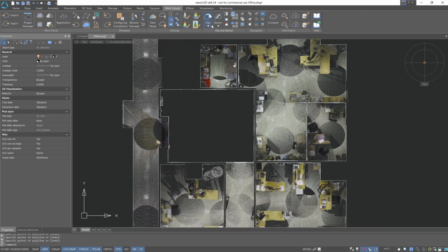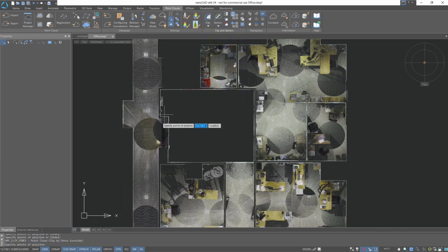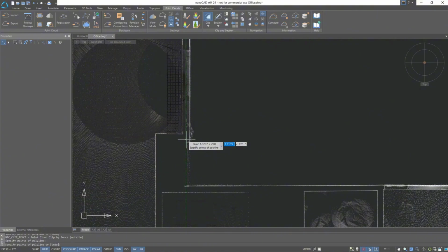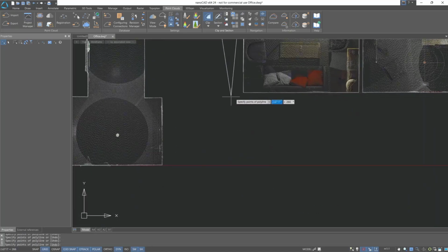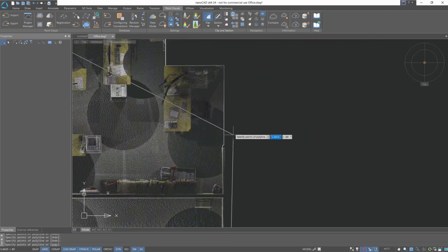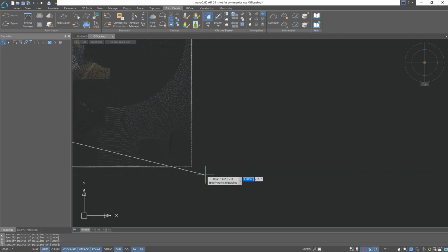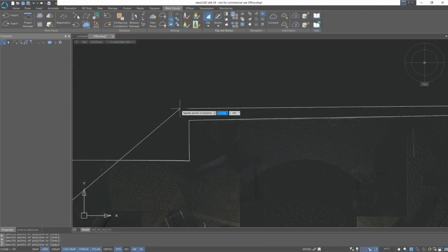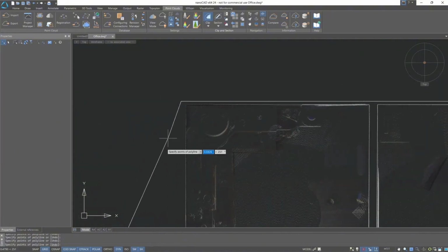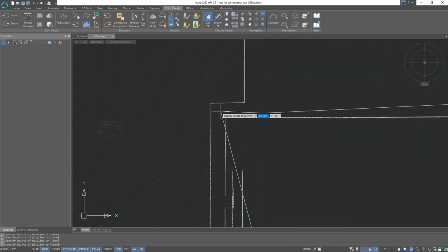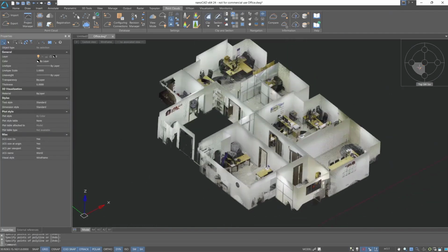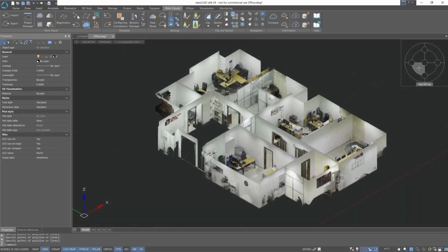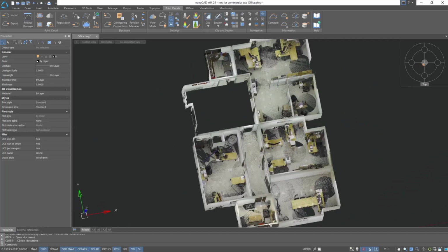Now let's use the Clip by polygon outside and highlight the rooms on the right, removing the other corridors of the building. Similarly, using the Clip by polygon inside or Clip by 2 points inside, highlight the corner points inside the remaining rooms. To speed up the work, I recommend using the space key to call the last command.